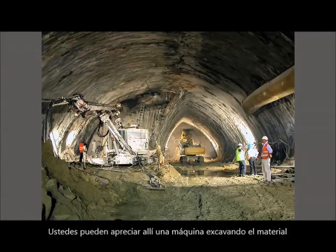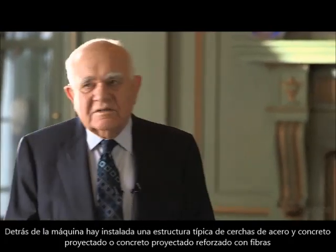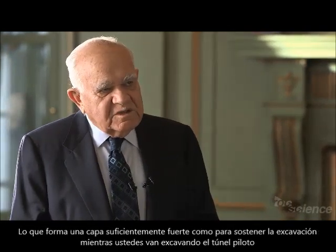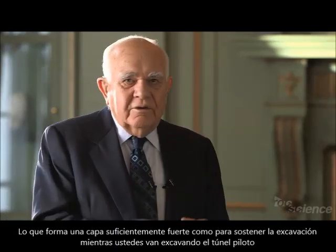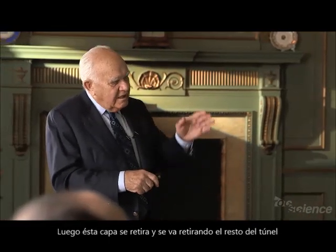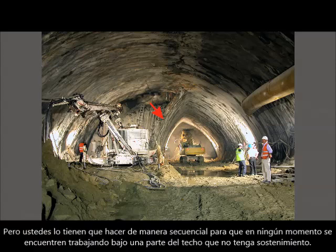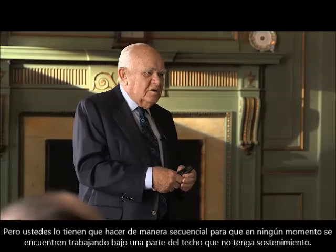So you see a machine working there, excavating the material, and installed behind it is a structure of typically lattice girders and shotcrete or fiber reinforced shotcrete, or some lining that is sufficiently strong to hold the excavation while you're creating the pilot tunnel. And then this wall is sacrificial, you remove that and you remove the rest of the tunnel. But you do it sequentially so that you are never allowing any area of the roof to be unsupported under which you're working.